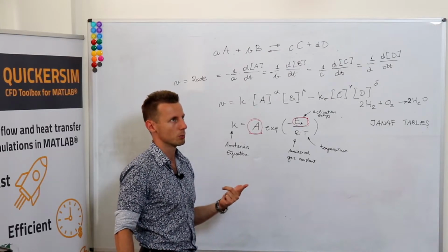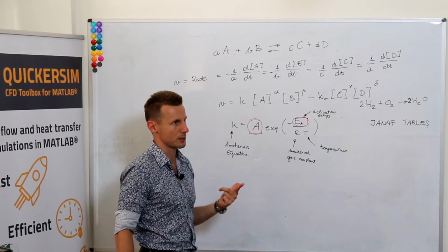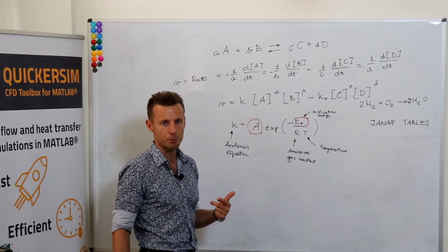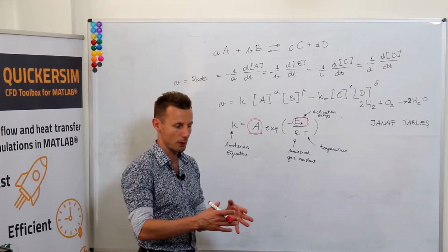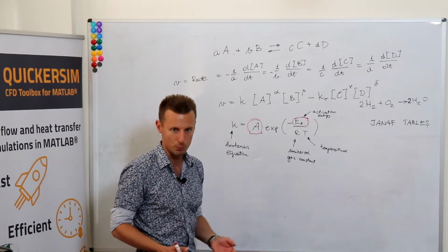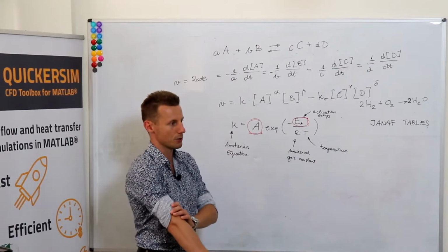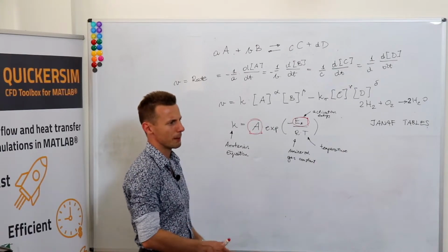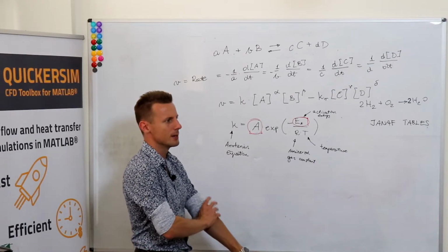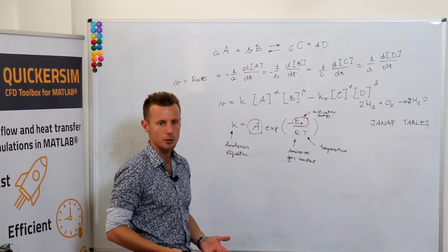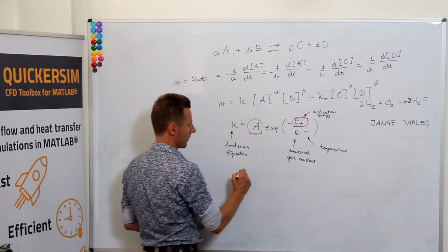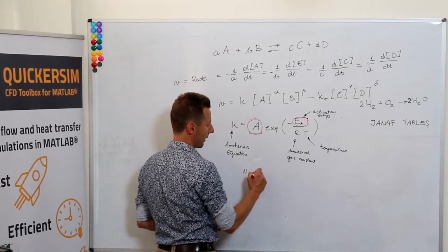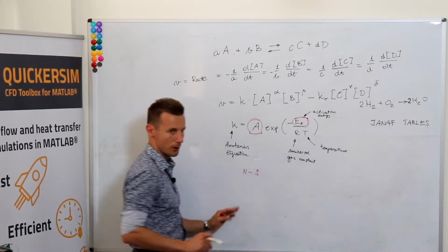So with very, very small exceptions, generally you cannot be modeling chemical reactions within this scope of incompressible Navier-Stokes equations. You would probably be able to do something like that for liquids. But for gases, generally, you need to cope with compressible Navier-Stokes equations. But then, generally, nothing changes to your Navier-Stokes equation.